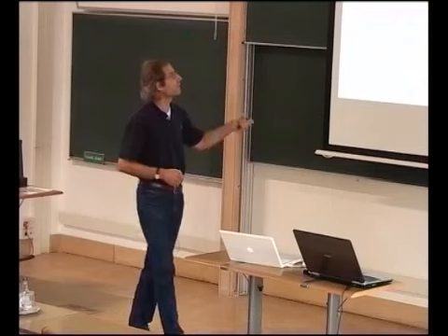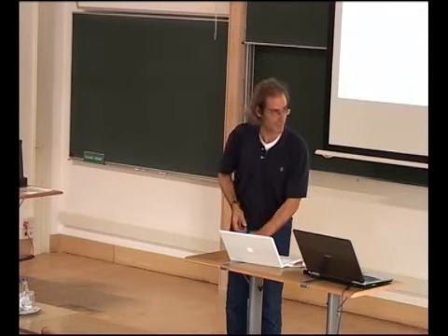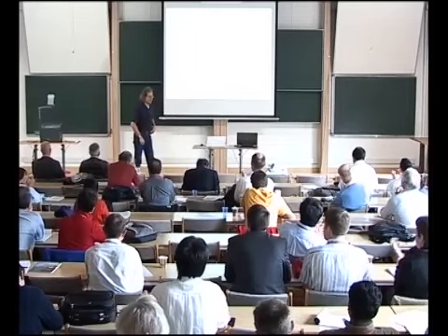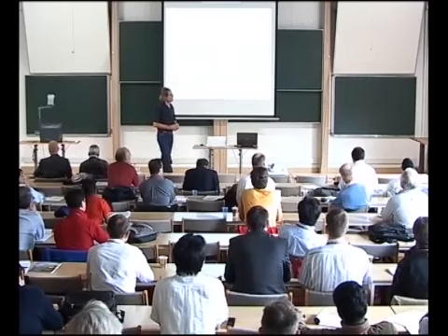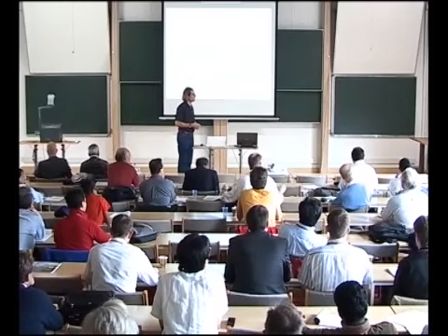Okay, so conclusion then, hopefully on time: the interaction does take place. It occurs via lambda patterns. The mechanism, which I just mentioned briefly, is the stabilizing effect, suppressing the Tollmien-Schlichting wave, but inducing secondary instability. And the competition between those two effects explains the difference between mode 5 and mode 2.